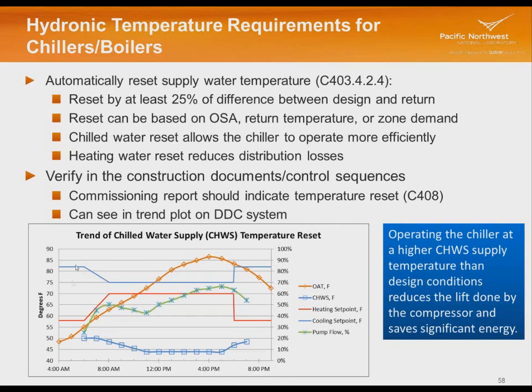And in the background here, we see a couple of lines. This gets back to this idea of a deadband. So here's our cooling set point. Here's our heating set point. You can see they're constant throughout the day with a good 5-degree deadband. We can see at the end of the day we have our setback. So the heating sets back to a lower temperature, maybe around 58 or 60 degrees, and the cooling set point goes up maybe to 80 or 85 degrees.